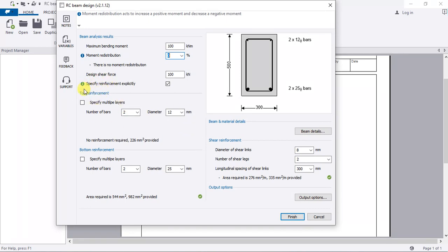You really have to know how to decide whether you need a top reinforcement or you don't need a top reinforcement. This is from calculation. You need to get the value of K. From that you'll know whether you need compression reinforcement or not.